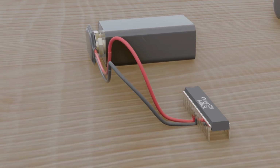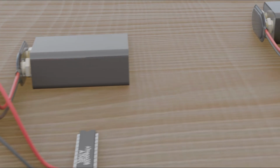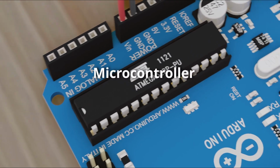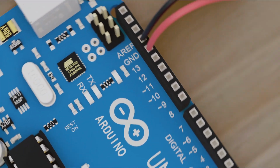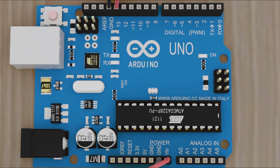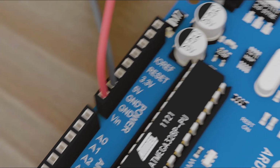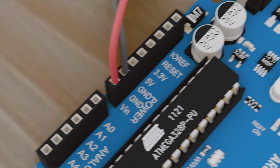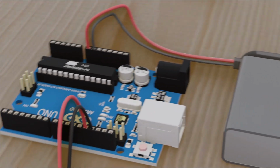Now, if you were to try and use this microcontroller chip on its own, you'd be stuck with needing to design a whole circuit board to make it work and to allow you to upload programs to it. Fortunately, companies like Arduino have already done the circuit board design with the microcontroller on it. There's a lot going on this Arduino Uno, but the main focus is the pins on the edges. This right here, VIN and ground, allow you to power the microcontroller by connecting VIN to the positive side of a power source and ground to the negative side. You can also power it with a USB cord or a barrel jack.